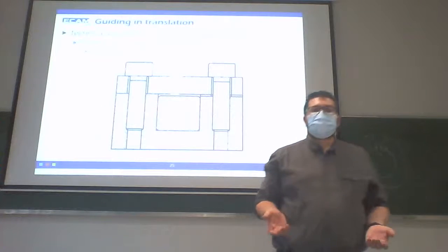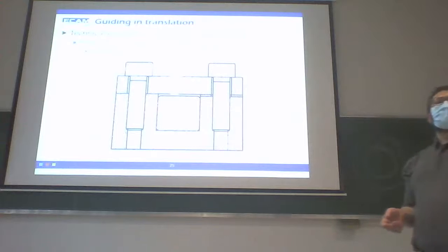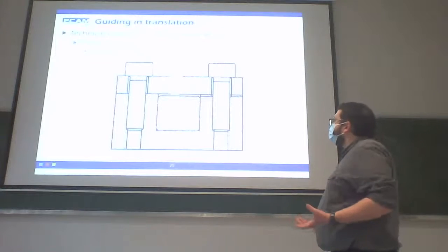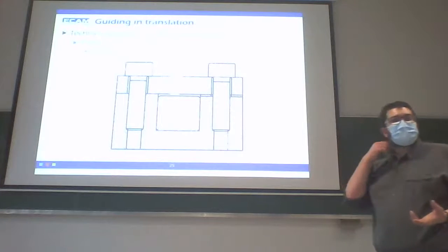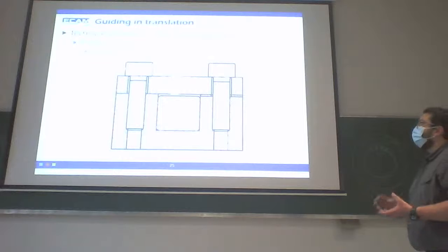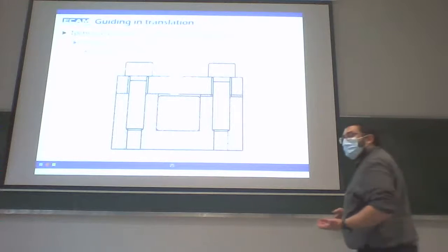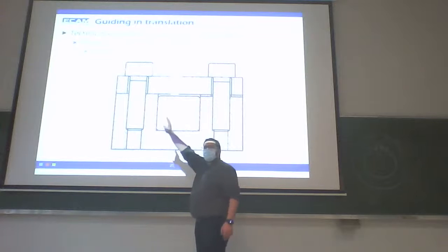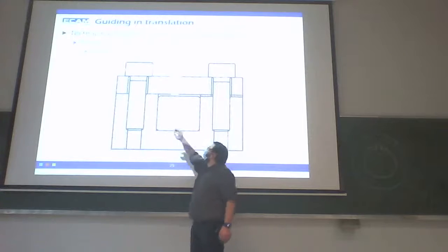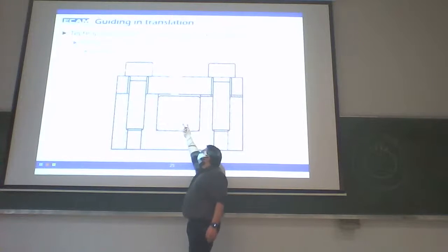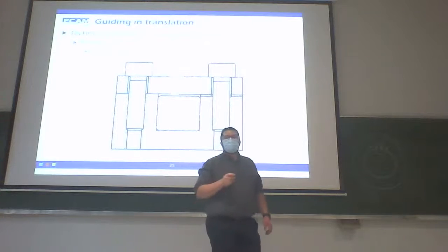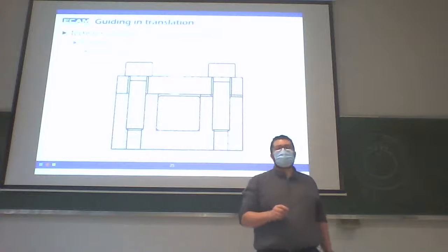The same with a square. With a square, I can stop the rotation. No possible rotation between two square parts. So here I realize a sliding joint, direction of the movement perpendicular to the screen. The square part in the middle slides inside the second one.